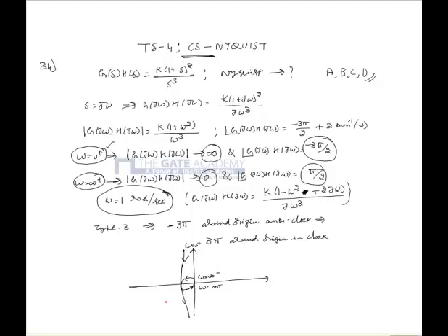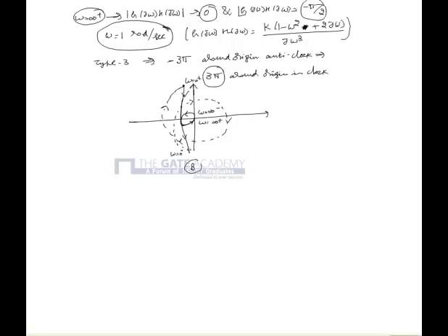And due to the symmetry, the Nyquist plot for omega equal to infinity minus to 0 minus will be as shown. And also we have seen that there will be an encirclement of 3 pi around origin in clockwise direction. So the Nyquist plot can be extended as shown. From this, we see that the correct Nyquist plot of the control system is as in B. So the correct option is